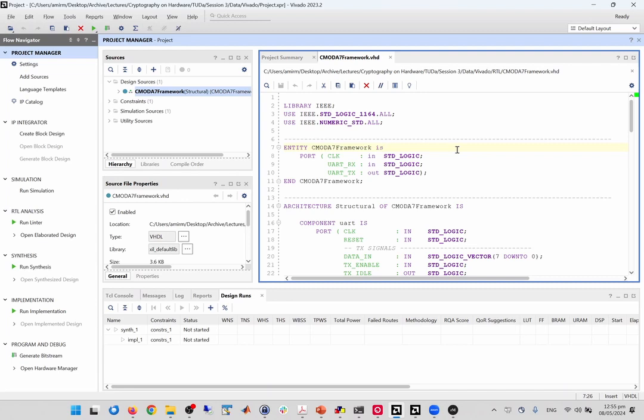This is the module that will be on the FPGA, and the primary input and primary output of this module or entity are exactly the I/O ports of the FPGA. Anything else which is inside the module and the lower hierarchy is not necessarily primary input or primary output. But everything that you give here will be primary input, primary output.